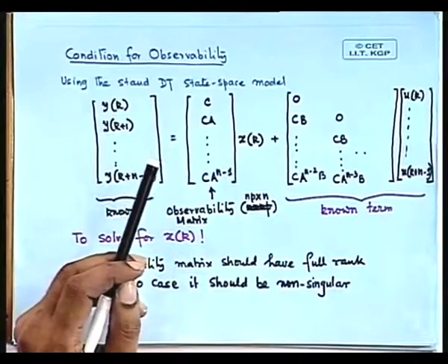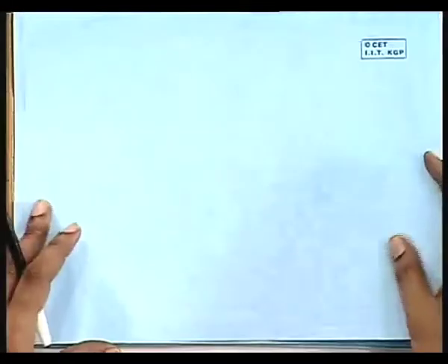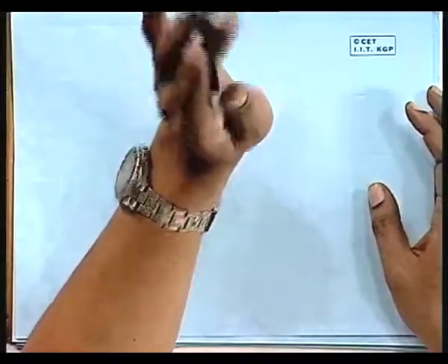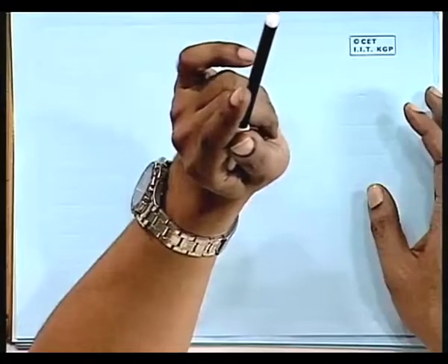And what are those equations? Why are these the equations? That is very simple, because you want to find out xk. Xk has how many components? Xk has n components. Let us say it is an nth order system. So if you want to solve out n components, you need how many equations? You need n equations. You need not only n equations, you need n linearly independent equations. So the first thing that we have to do is set up those equations and then solve them, right. And these equations must be set up with u and y because they are what we know.